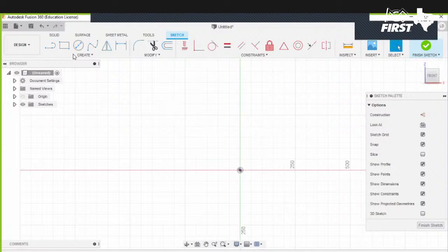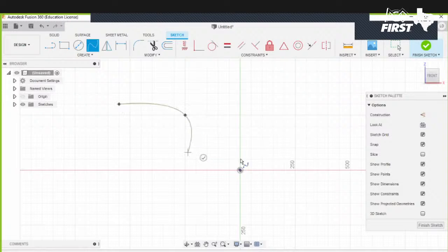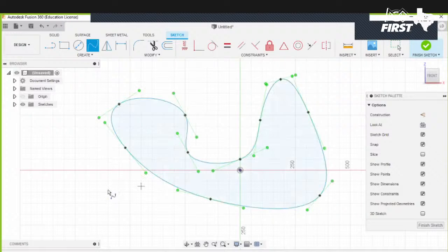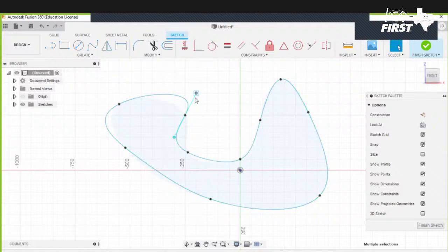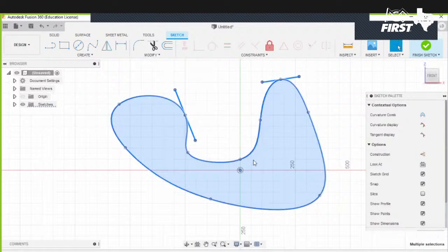And the last thing we can try is that spline. Let's do it really quickly. So with spline, we can make a bunch of points, and notice how it follows me. Whatever point that I make, it makes a line based on those points. Notice how, like the vertex function, I can control the slope or the derivative of each point, which is useful. And it's like the other side, except it has its differences between the two. It depends on what you need. Both are very versatile. So let's go ahead, exit out of that, delete that.